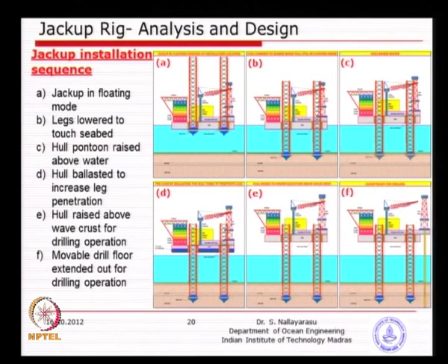There are various sequences, I just put them out in a sketch form, so that you can easily understand. Jackup in floating mode, which is going to come from another location to the location of interest. Legs lowered to touch seabed, which is this one. That means still in floating mode, the legs are just allowed to go down using your drives and rack and pinion arrangement, which can bring them down.